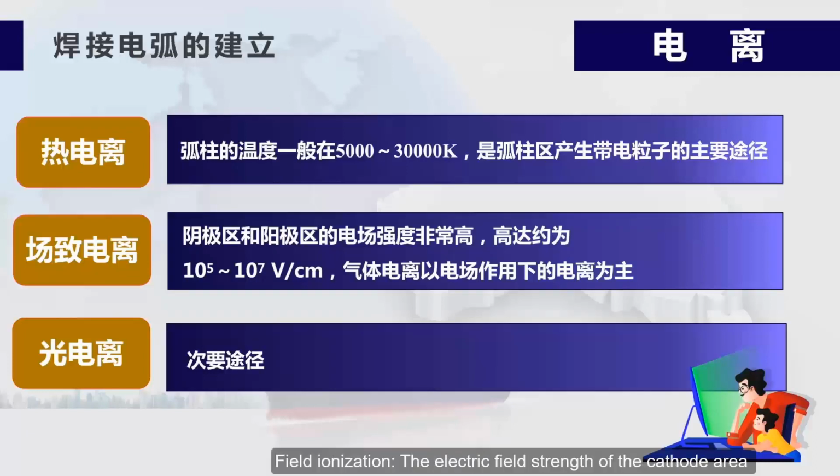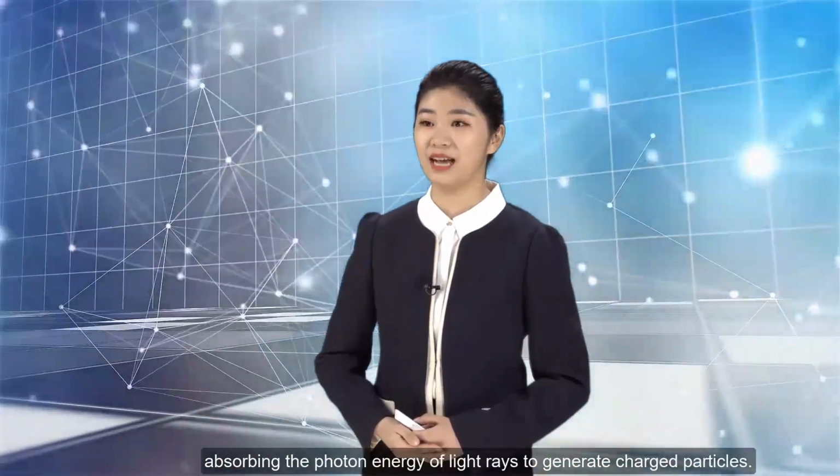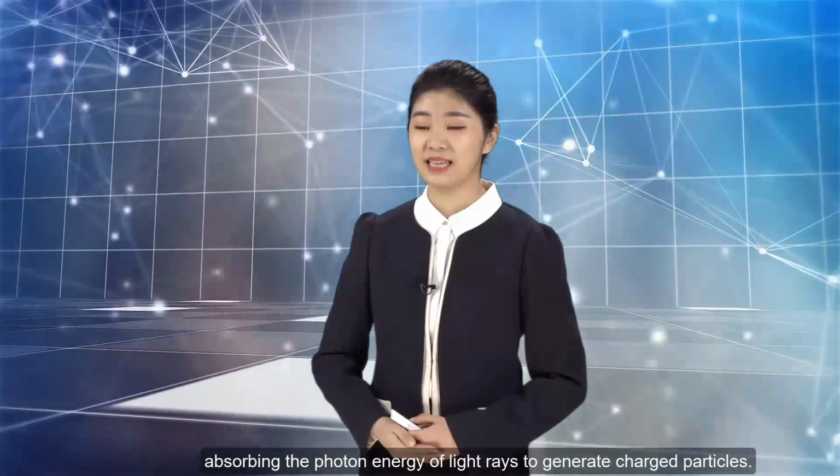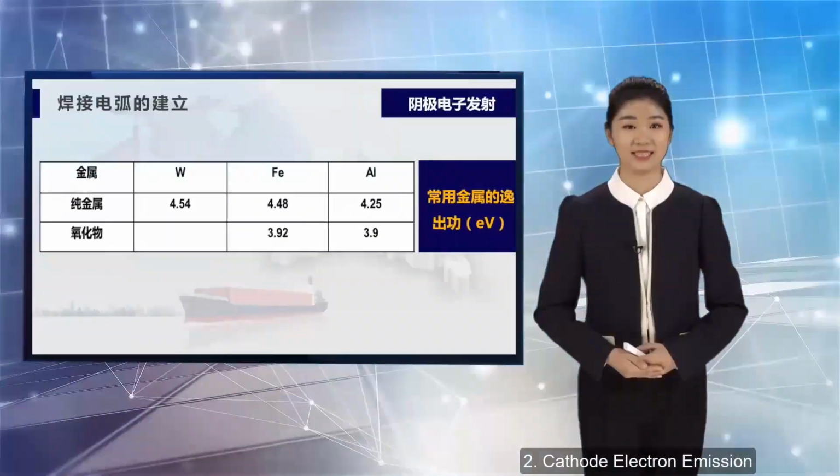Field ionization. The electric field strength of the cathode area and the anode area is very high, and the gas ionization is mainly ionization under the action of the electric field. Photoionization. It refers to the ionization generated by gas atoms, or molecules, absorbing the photon energy of light rays to generate charged particles. 2. Cathode electron emission.